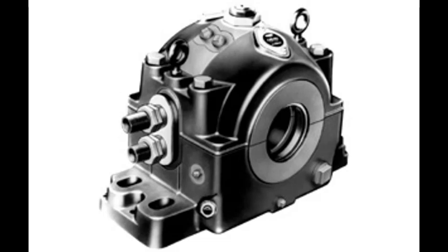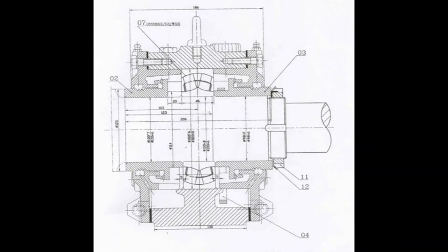For the supporting arrangement of these fans, we have sleeve type Dodge Palmer block bearings, which are journal bearings. They are supplied with oil ring based lubrication arrangement, and these bearings are preferable at speeds of 1000 to 3000 rpm. When speed is less, we have double row roller journal bearings, which are rolling contact anti-friction bearings, and they are grease lubricated.